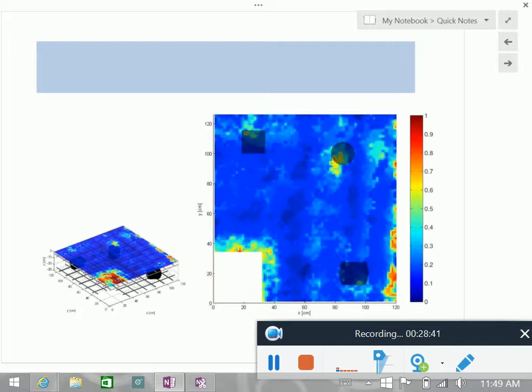Now the boundaries for impact echo, we understand why you would get that: when you are close to the boundary, you also get reflection from the boundary, so the peaks become wider. So that's why this is also larger. But that's a false positive, and in practical applications it's always a danger. Where is that coming from?